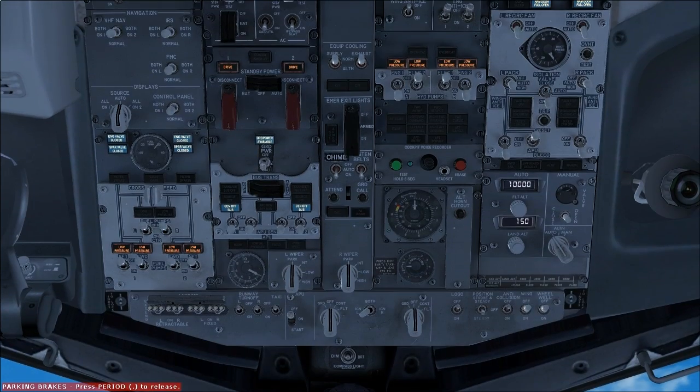And the next stage of the flight is the cruise altitude, which we're going to be at 28,000. And our landing altitude will be 2,180 feet. It's 2,150, sorry. Next our lights. Logo on, position steady, anti-collision off, and wing illumination you can have either on or off, but since it's daytime we'll just use the off position.